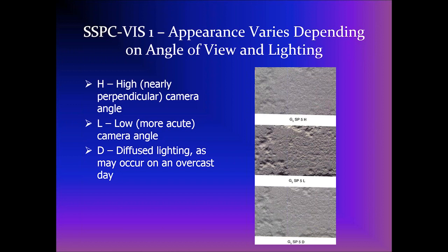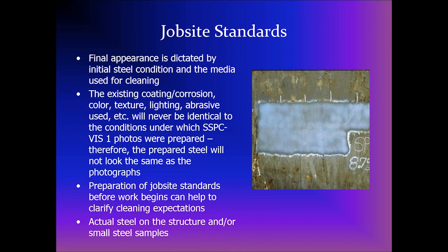The point being, the time of the day that you inspect the surface can affect the appearance. In order to really use the standards and the reference photos, it's best to do job site standards, because in this case you're really incorporating the effect of the steel, the abrasive, the existing condition, the profile, everything into that test area that you can't find in photographs alone, because photographs will never look like the surface.